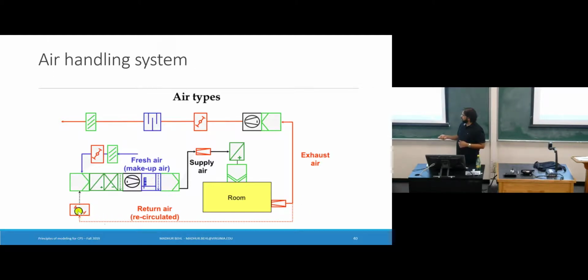The percentage of this mix of fresh air and recirculated air is decided by some valves or dampers. Right? If they are fully open, then you are just taking in everything. So this air comes in. Within the AHU, it gets treated for particulate matter, for temperature, and for humidity. And I'll tell you how that happens. But the output of the AHU is some supply air.